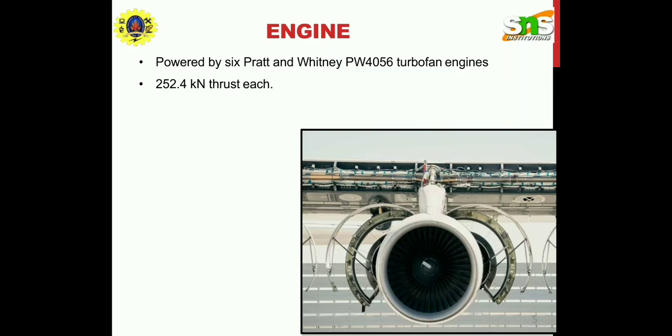Reaction turbo machines operate by reacting the flow of fluid through aerofoil shaped rotor and stator blades. The velocity of the fluid through the set of blades increases slightly as it passes from rotor to stator and vice versa. Newton's third law describes the transfer of energy for reaction turbines. A pressure casement is needed to contain the working fluid. For compressible working fluid, multiple turbine stages are usually used to harness the expanding gas efficiently. Most turbo machines use a combination of impulse and reaction in their design, often with impulse and reaction parts on the same blade.